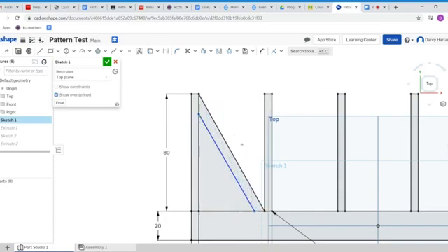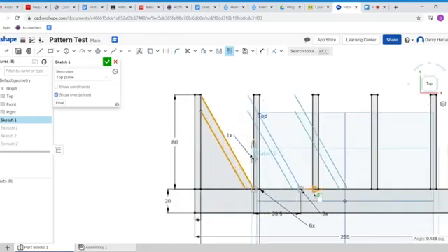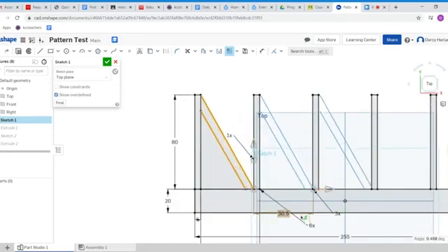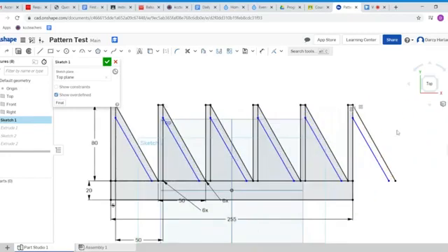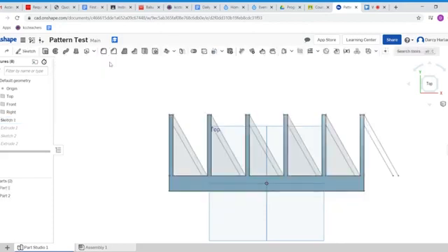I wanted some triangle shaped beams, and then I wanted to have a linear pattern on those moving the same direction. Okay, you can actually drag these out as well, and I want to repeat it 6 times. There we go. And then I click off the image when I'm happy, and now you can see we've got some of those horizontal beams as well.